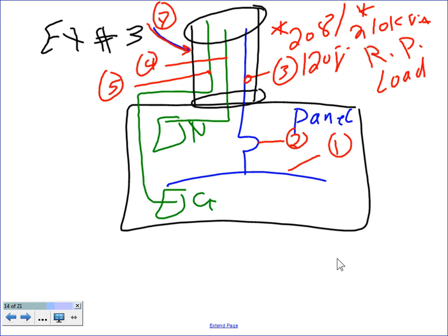So here's what we need to do. Number 1, the panel size. Number 2, the overcurrent protection device for the panel. Number 3, the 3-phase conductor. Number 4, this time, the neutral conductor. Number 5, Chris, I changed 5 for you: this time it is the equipment grounding conductor. This is not a service panel, so there is no grounding electrode conductor and main bonding jumper. They don't exist because this panel is not a service entrance panel, and we're not doing the bonding inside the panel.